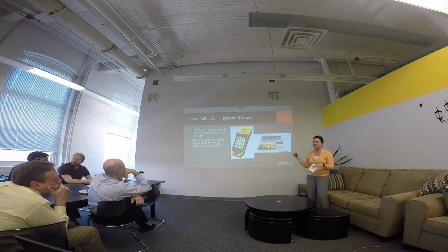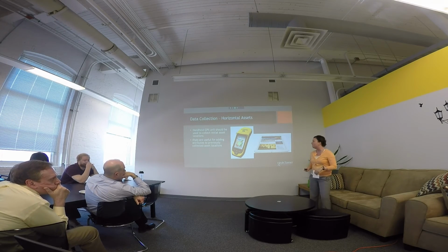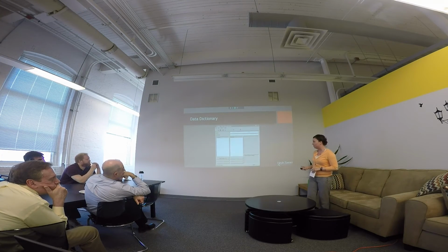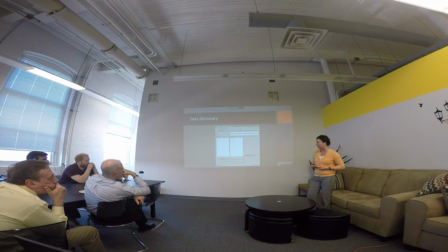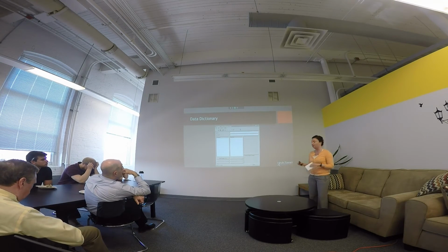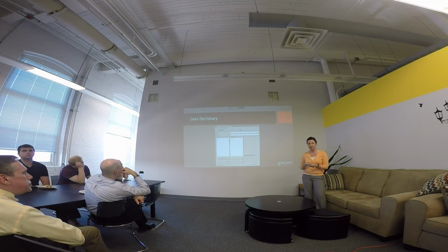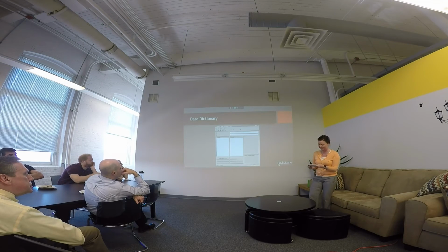So like I said, the iPads are useful for collecting things like attribute information. But the Trimble handheld also can be, it just requires an extra step. So that leads us to data dictionaries. Basically, the real power of the GPS lies in the data dictionary. A lot of people don't understand them, they don't use them. It took some digging, but I get it.